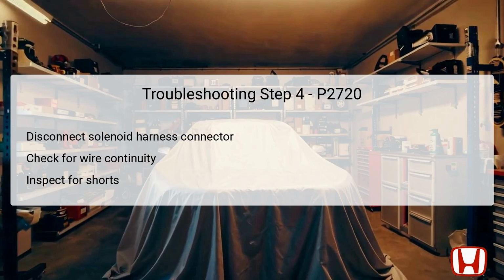In this fourth troubleshooting step, the focus shifts to checking for shorts in the LCC-LS line wiring. Start by disconnecting the solenoid wire harness A, 8P connector. It's essential to ensure the vehicle is in off lock mode to prevent electrical accidents during testing.